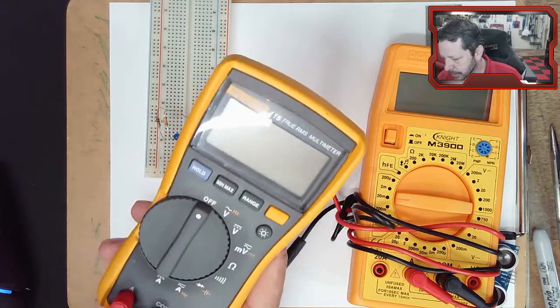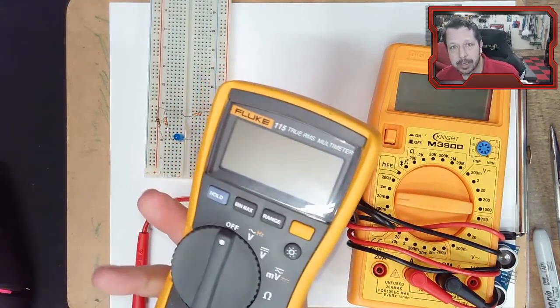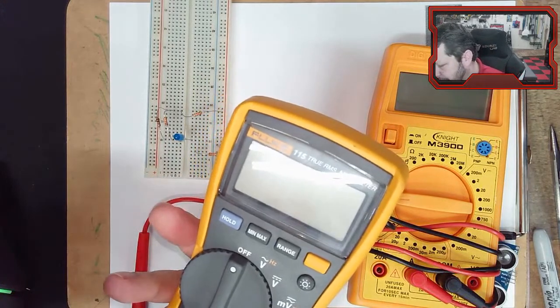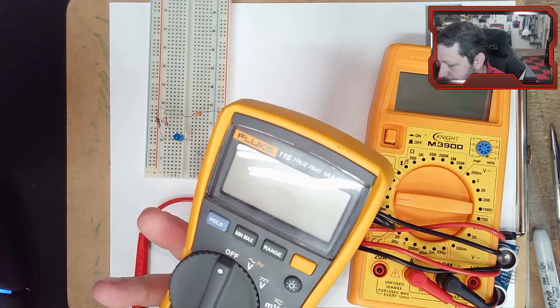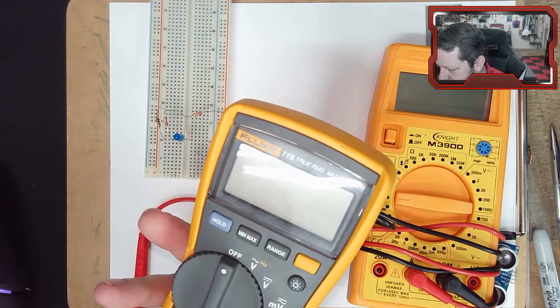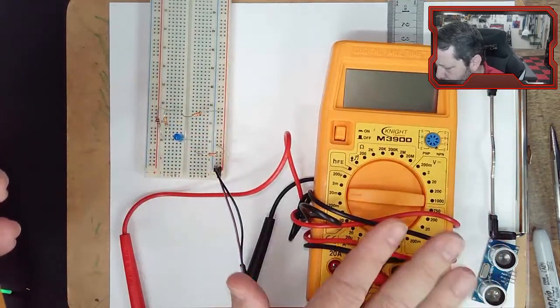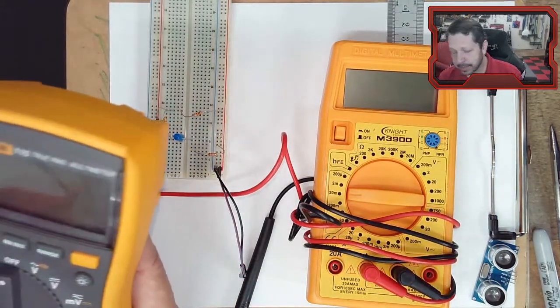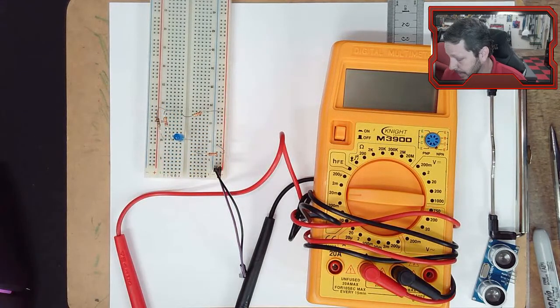The third thing that was just kind of out of our control was we did open this one up and look inside at the fuse. It has one of those large bus fuses in it. At the time, I didn't have a way to check if that was good or not. So I went and found one of the cheap multimeters that I have, and it turns out that fuse was blown. So I ordered a new one. We'll replace that sometime once it gets here. I don't know how long it'll take to get here.